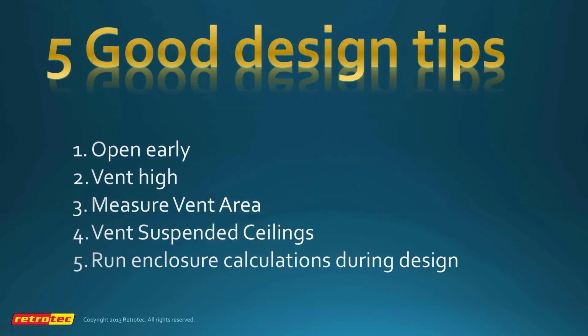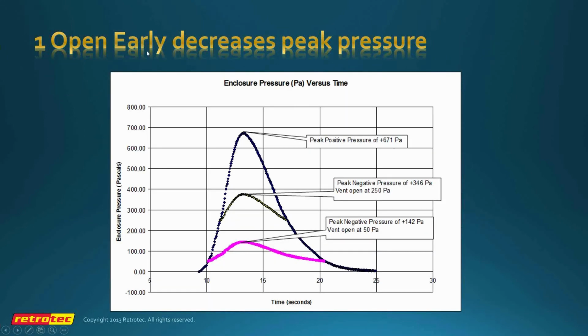Just briefly touch on some design tips. Again, if you've got any questions as we go, I'm more than happy to respond to them. So the first thing is that let's just take a look at these slides here. That the PRV should open early, and all of these PRVs need to be measured to see at what pressure they open. I prefer that they open at around 75 or 100 pascals maximum, so that we start to relieve the peak pressure early. And here we show a